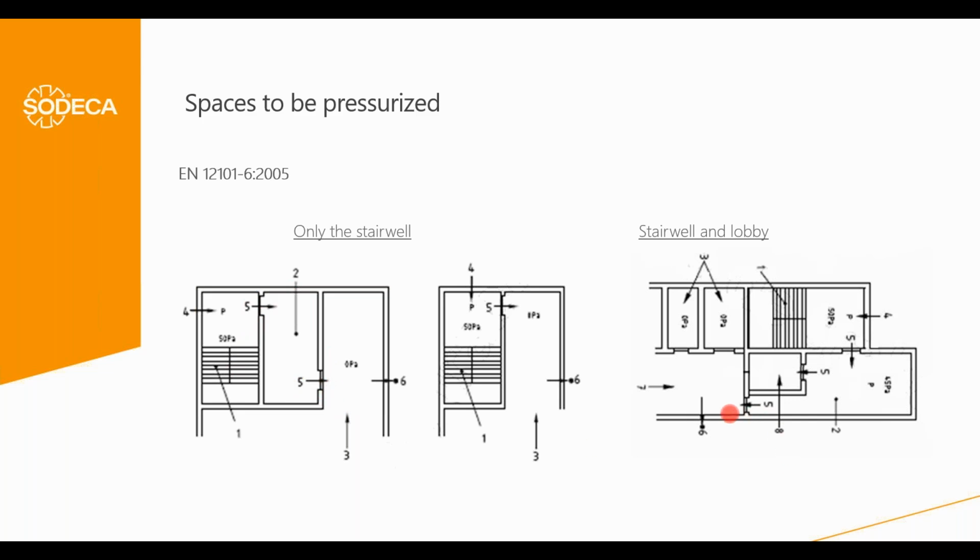In the other case, when we have the lift shaft, we cannot ensure the level of overpressure of that lobby, because the air leaking through that door will escape to the lift shaft, but also to the main level. So the level of overpressure of this lobby will be smaller, and then there is the risk that the smoke leaks into the lobby, into the lift shaft, and through this lift shaft into the lobbies in other levels.